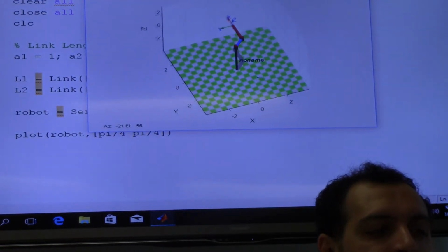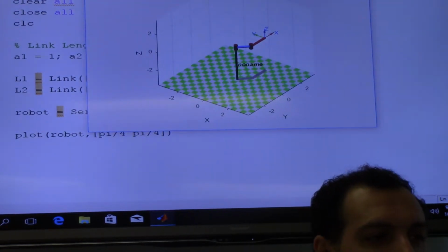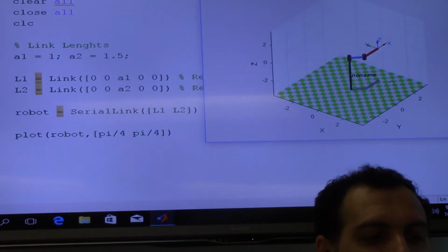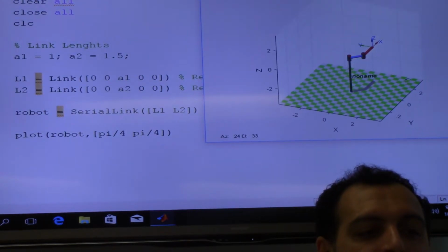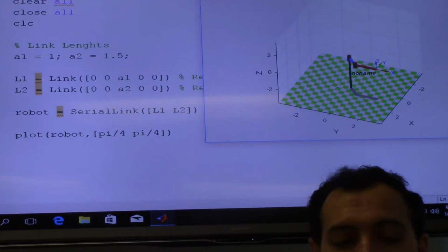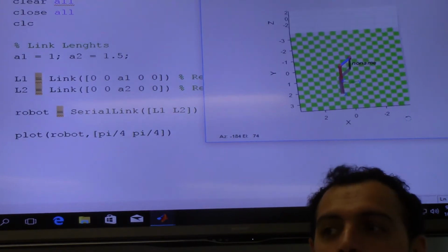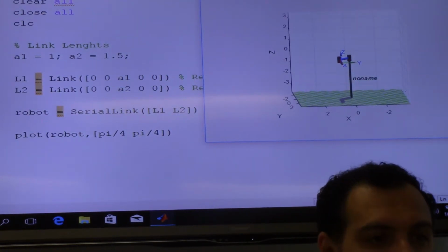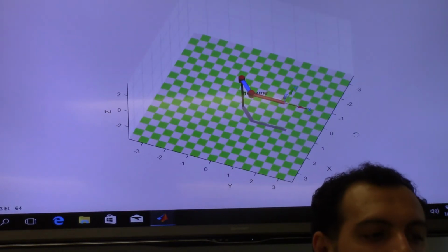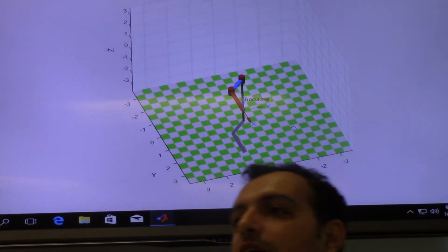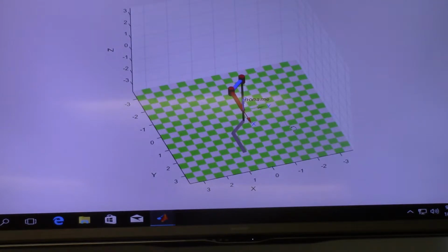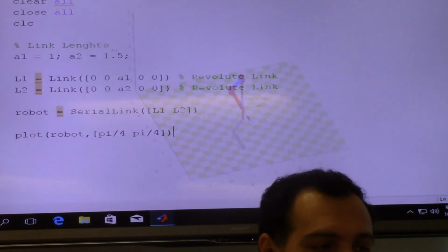So here you'll see a manipulator, right? Once you plot that, you'll see a manipulator here, like this. And you can see the axis of the end effector. You'll see the 3 axes. Okay, these are the 2 joints. Now, this is okay, but if you want to actually run this, in practice what happens is every manipulator comes with a teach pendant, so you can move the joints independently. So what we'll try to do is we'll try to emulate that in a program.